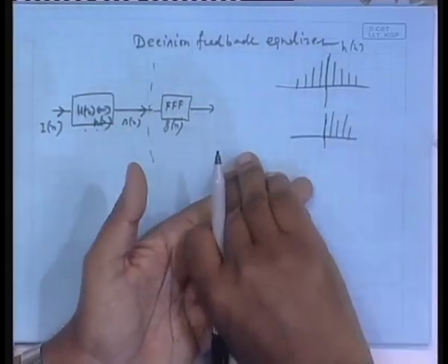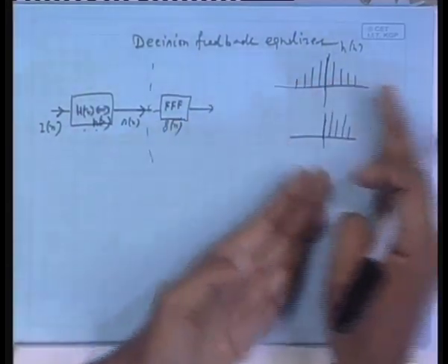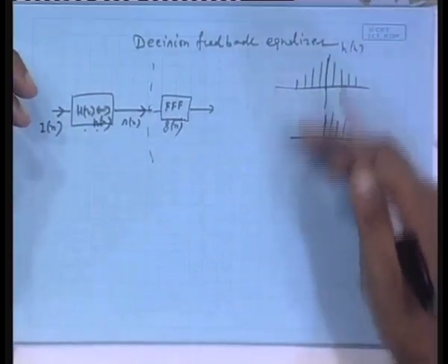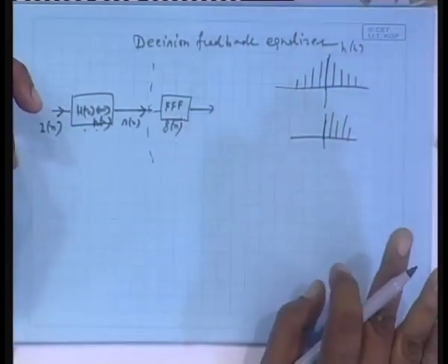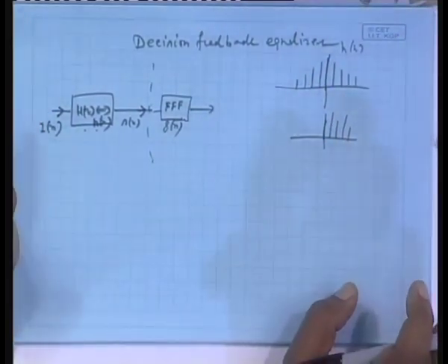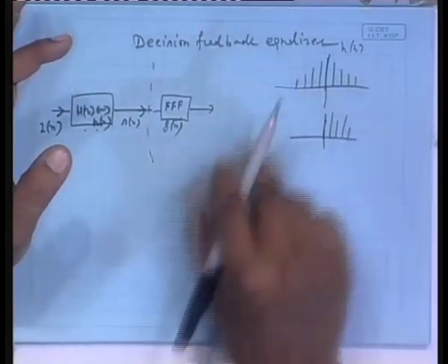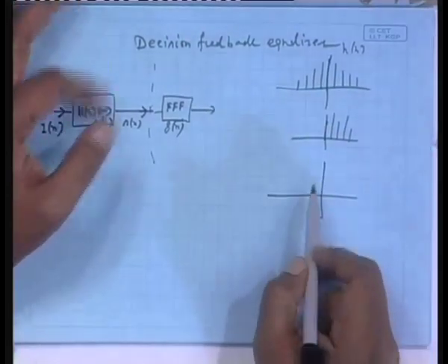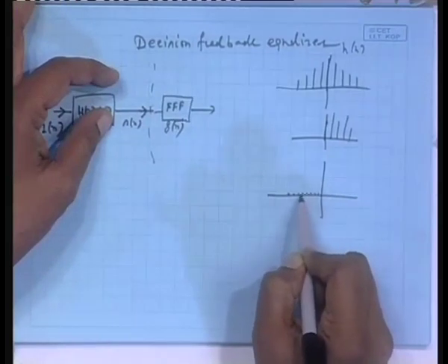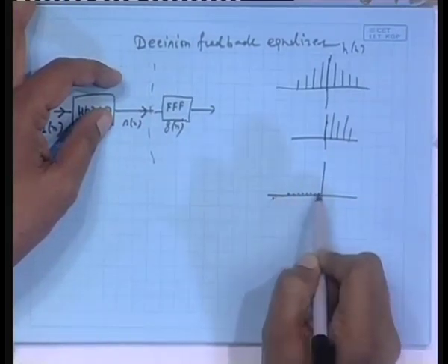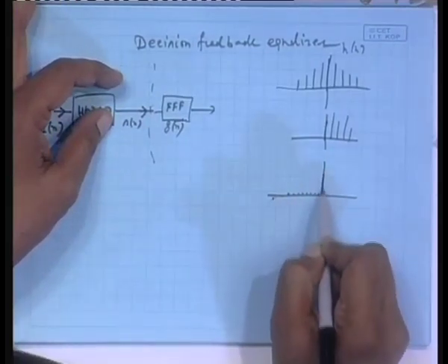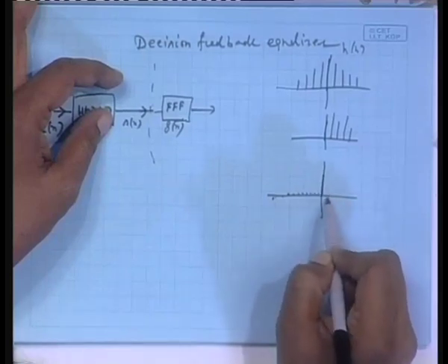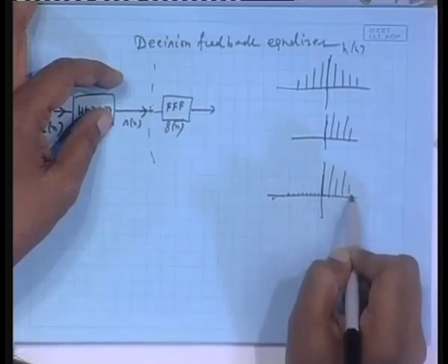You reverse it and then go on shifting this way or that way and find out overlap, sample wise multiply and add. That is the way to convolve. You design it such that on this side, this is our result, you have got very low value, almost 0, and from this point onwards you get some values up to some point.